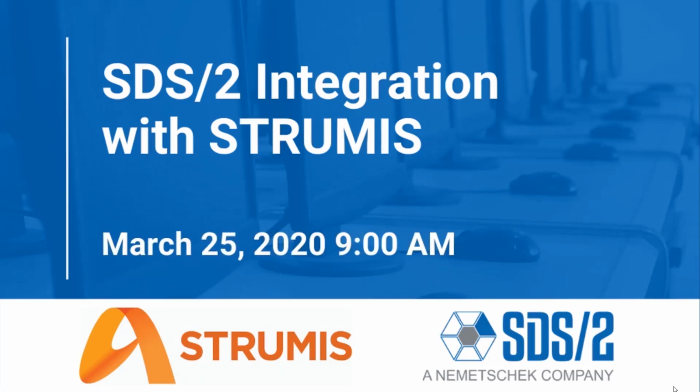This is Brandon from SDS2 here. A question that someone may have is how is SDS2 getting this information out of STRUMIS? And in fact, we already saw that settings screen from our plugin. It's a plugin, and we have access directly to the STRUMIS database through a plugin. And every time that you hit that color by attribute tool, it goes and queries the STRUMIS contract that has linked to this job, and refreshes the data.